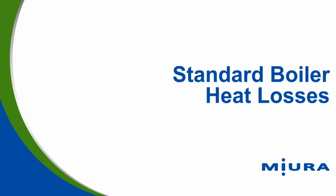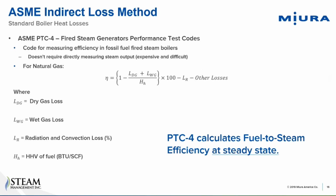So yeah. All right, so we'll move on to standard boiler heat losses. When we're talking about boiler efficiency, what are the typical losses? We'll use the ASME indirect loss method to talk about that. Basically, that comes from ASME PTC4, which is a performance test code. It's a pretty long code telling boiler manufacturers and customers how to hold boiler manufacturers accountable for what they say they're going to sell you, and how we measure that efficiency to prove that's what we sold you.